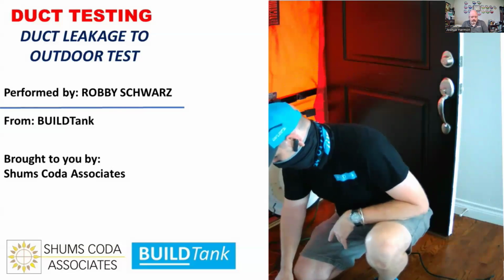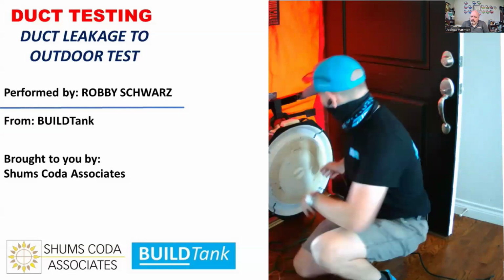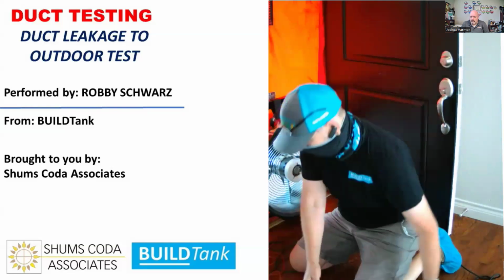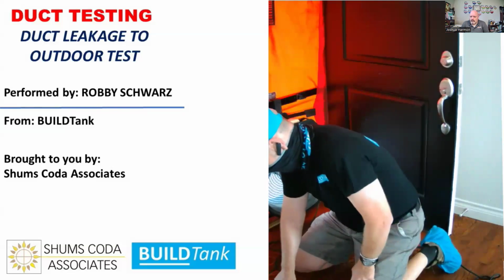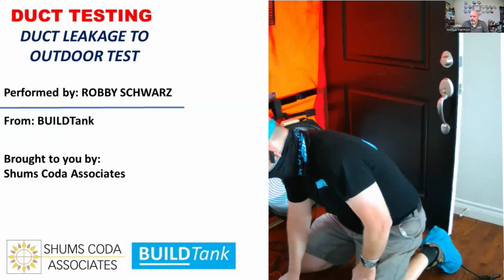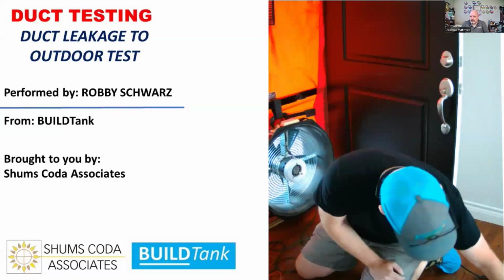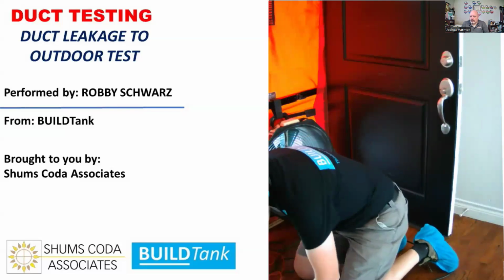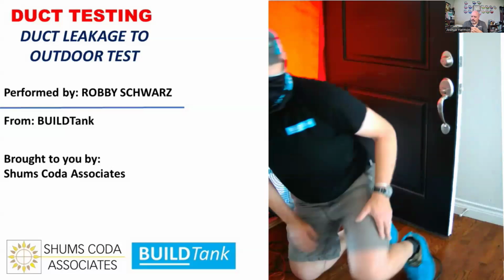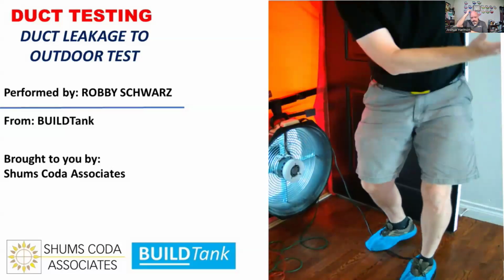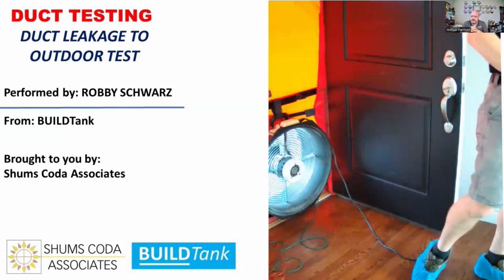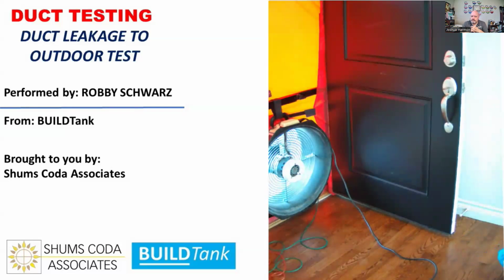Okay, the next thing we're going to do is pressurize the house to 25 pascals. That's going to be our reference pressure in the house. And I'm going to let the fan cruise. But I need to turn on the fan. So air is now coming into the house. We're blowing up the house like a balloon in essence. And I'm going to connect the duct system to this air that's coming into the house.